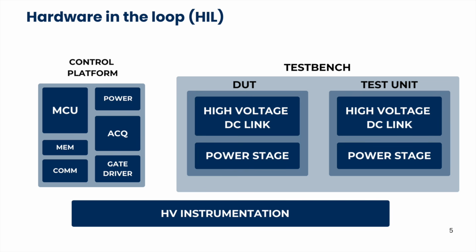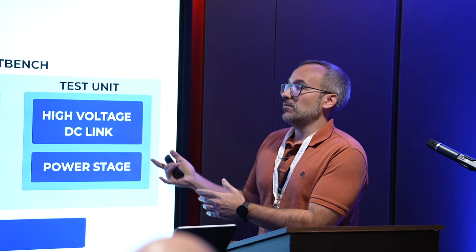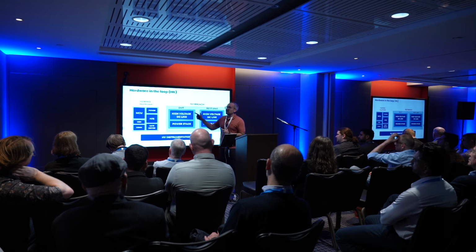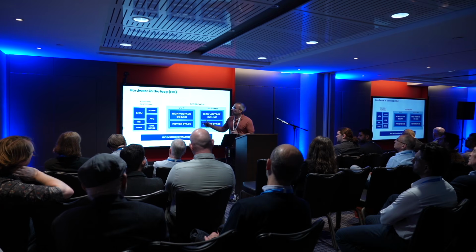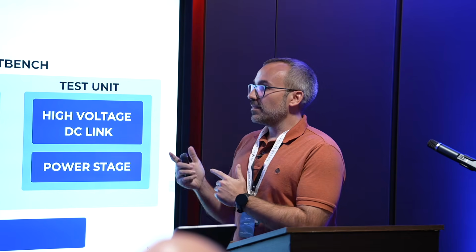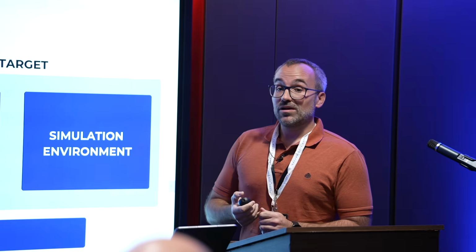In addition to the test bench and the control platform, we will need to take measurements from the test, from the device under test and the test unit. So we're going to need high voltage instrumentation in order to take measurements of high current, voltage, and high power. This will work, and it is still working today in many different companies. However, it is a little bit dangerous because here you will have real power, real voltages which are moving within the test bench. So this problem is, as I said, not a new problem, and the industry has some fixes for that. For example, hardware in the loop.